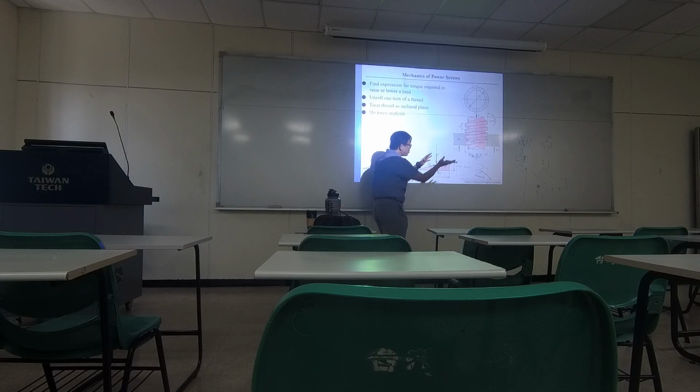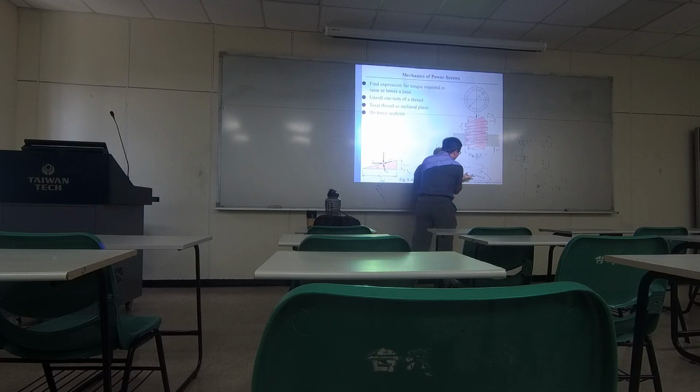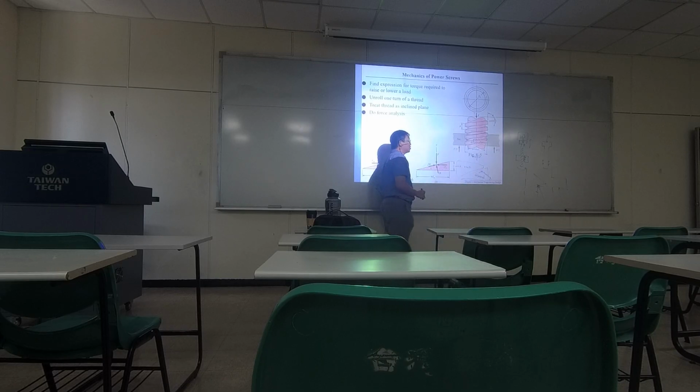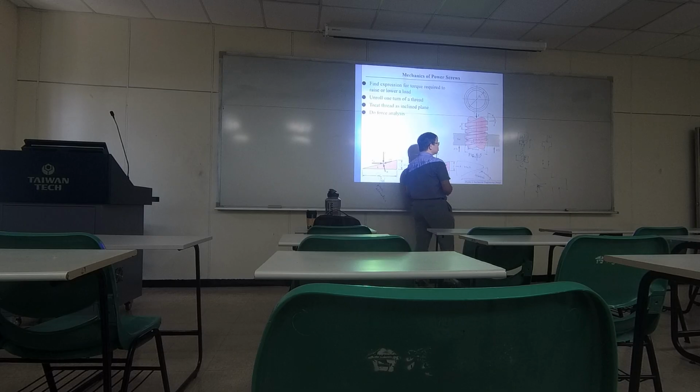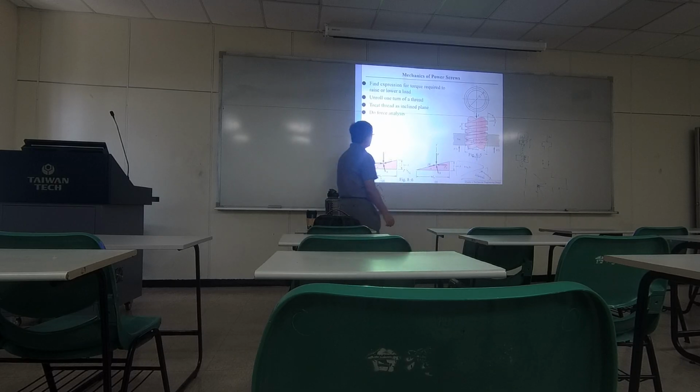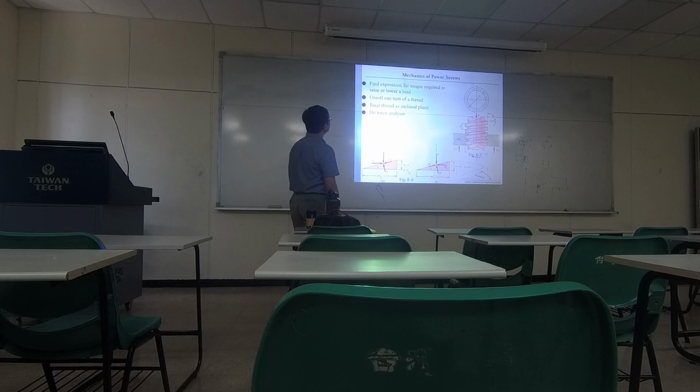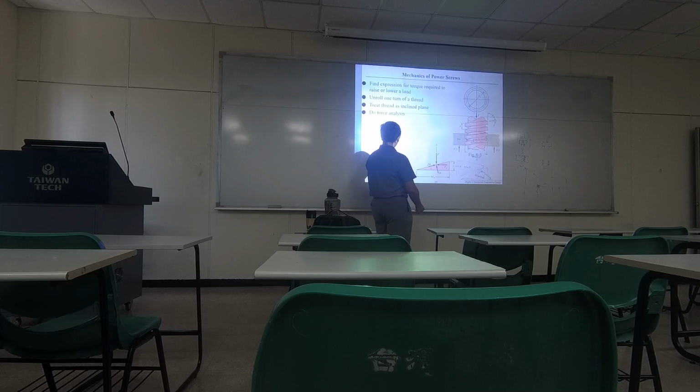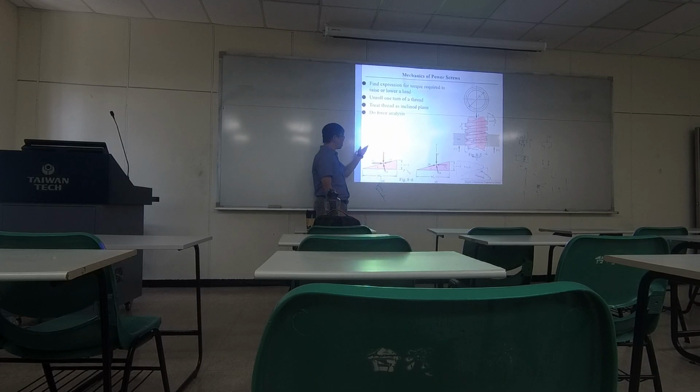You're moving the thread along this interface. So if you're moving this way, then your friction should follow the direction that is against you. So your friction force would be going down if you are lifting. I think this is a lifting case. Because you are moving up, your friction force goes down.